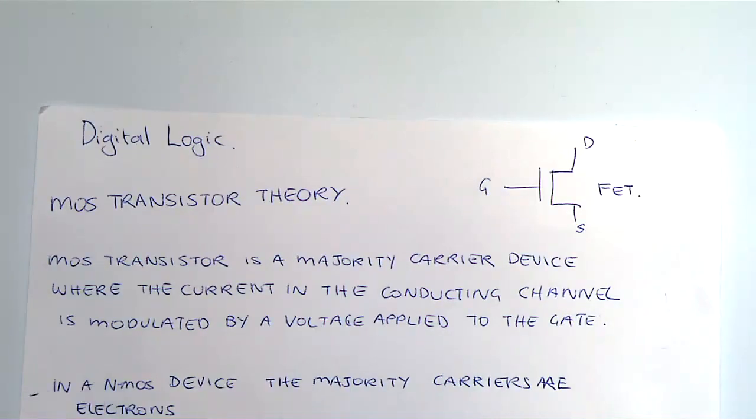Okay. So you put some current into the base, and you've got some current amplification, a beta factor, and that actually controls the current that you get out from the collector to emitter, right? So you get beta times the base current gives you the current through the collector, and the total current is beta plus 1 times the base current. Okay.